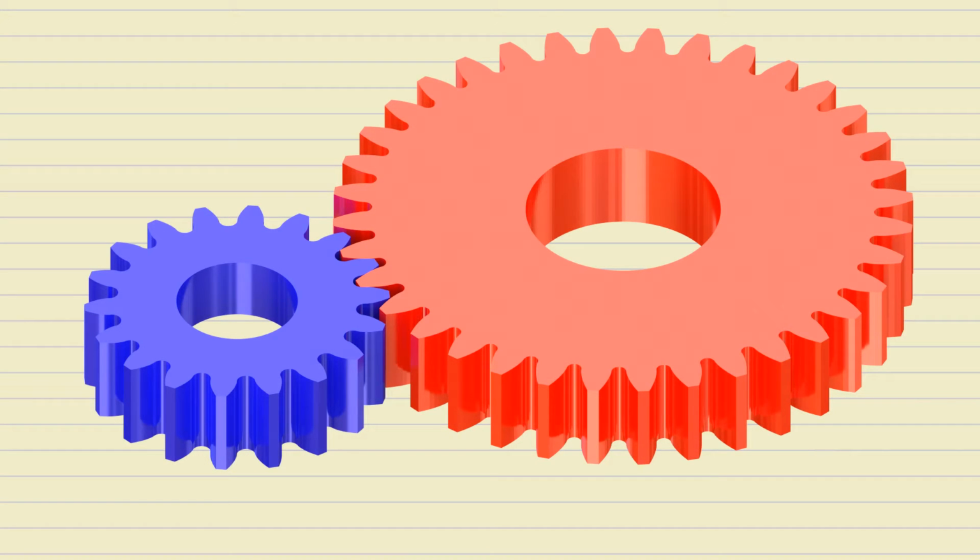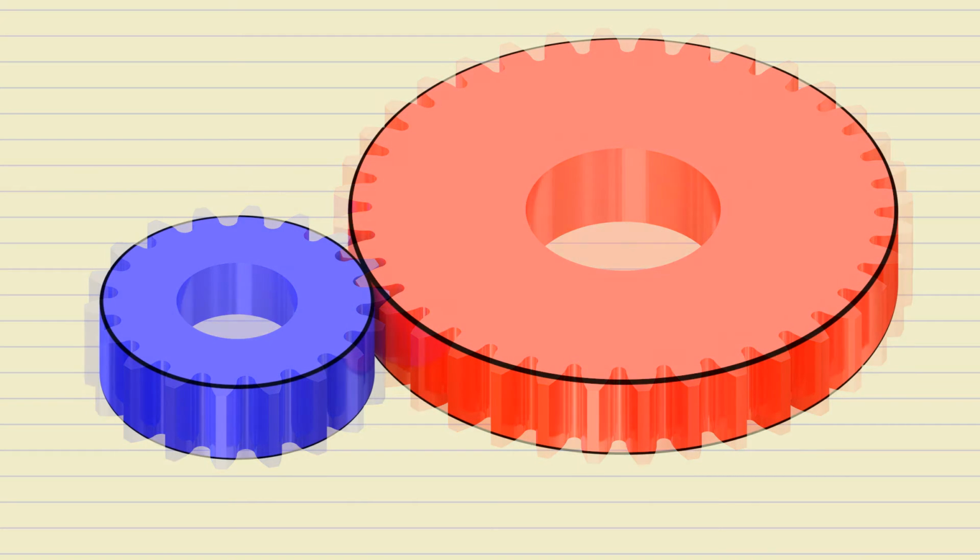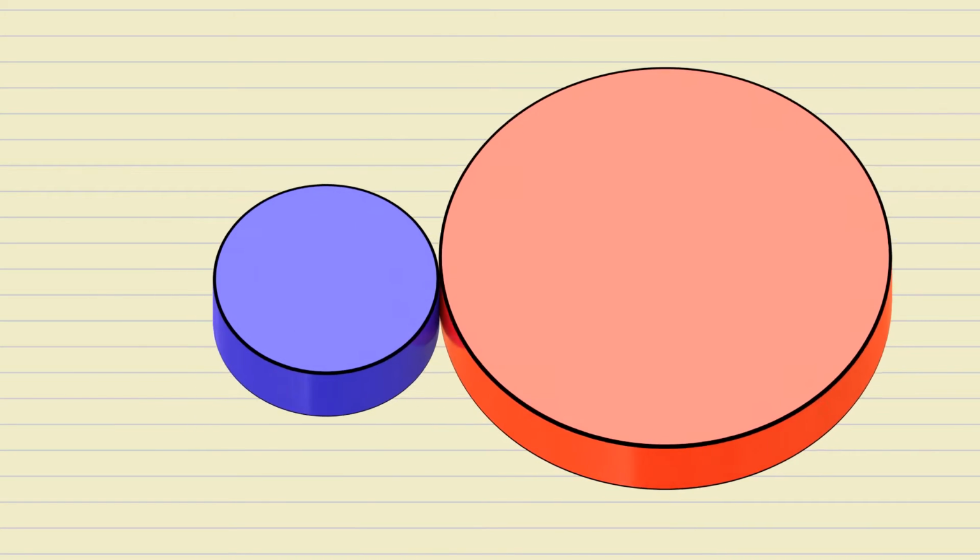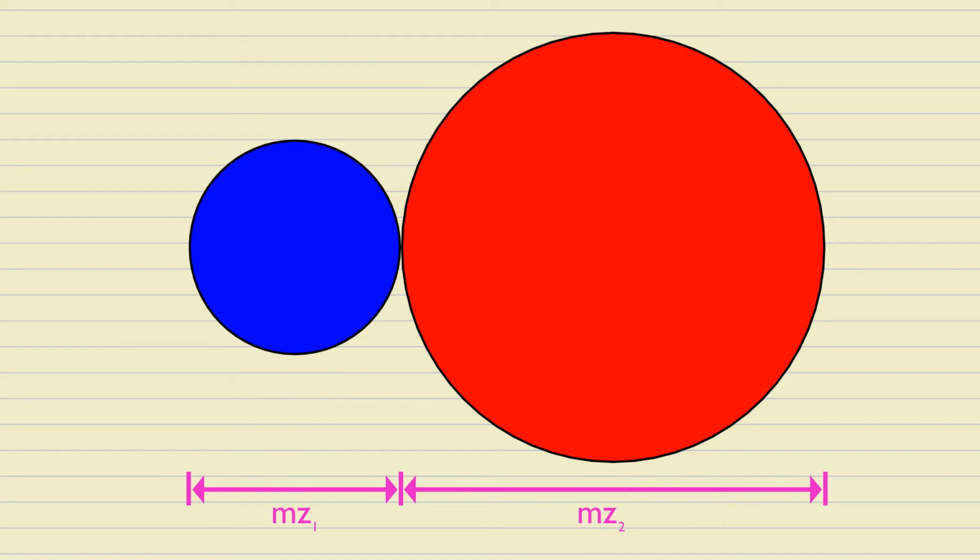Let's take a quick look at the regular gears, known as spur gears, first. Conceptually, a pair of mating gears can be represented by two touching cylinders. The bases of the cylinders are called the reference circles. A spur gear system can be fully defined by as few as 3 parameters, the number of teeth in each gear, and a number, called module, shared by both gears. The module determines the diameters of the reference circles, known as the reference diameters, calculated as the product of the module and number of teeth.